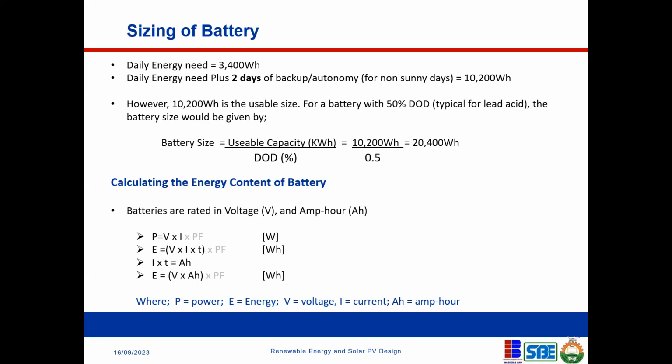And that's where you now begin to recommend the kind of inverter that you need to install. Should you use a hybrid inverter that could charge from the solar panel and also from the grid? Or should you use just a battery inverter that is not hybrid, that will maybe charge only from the solar panel, right? So there are strategies to this.